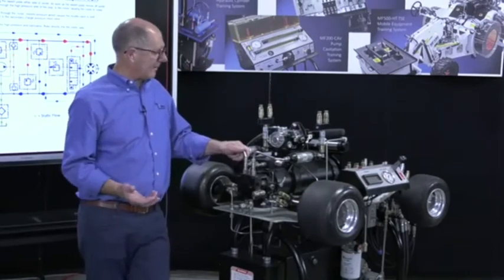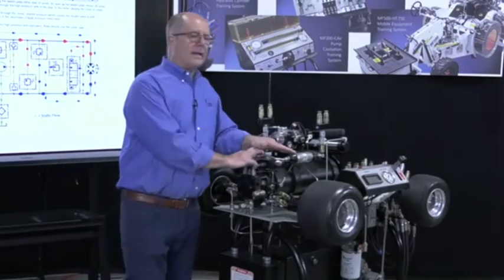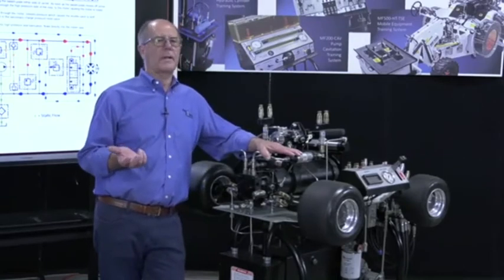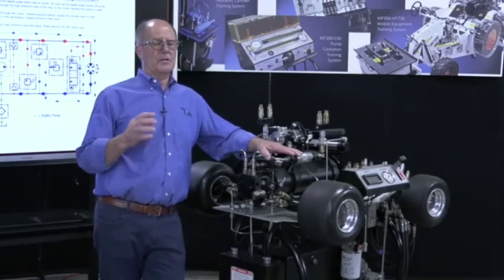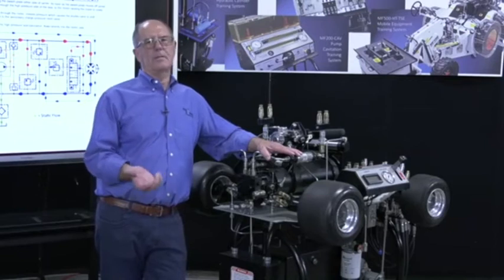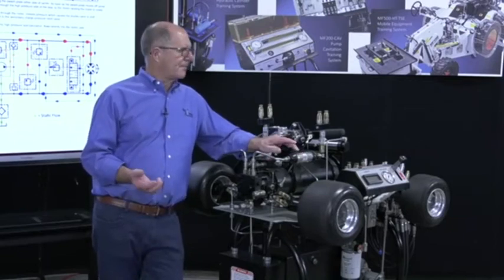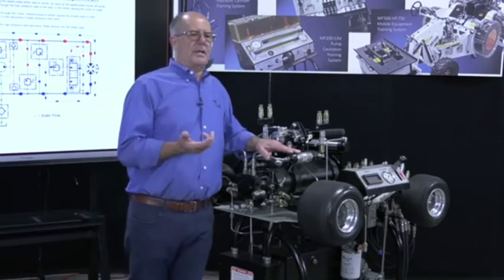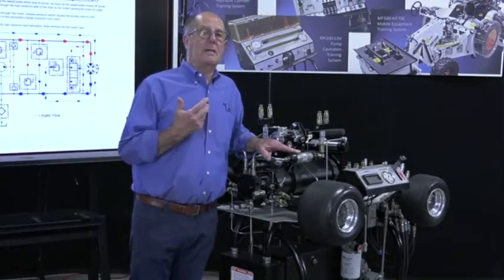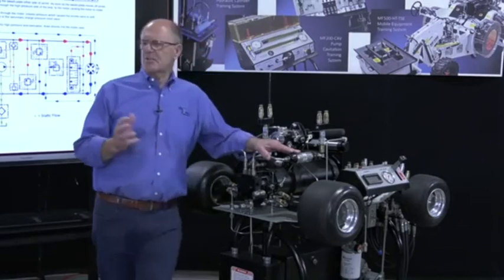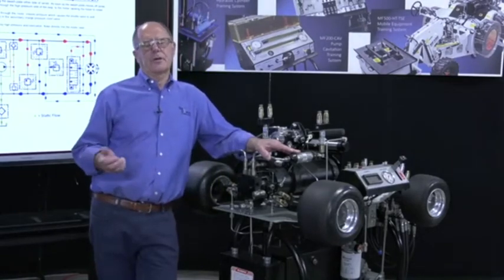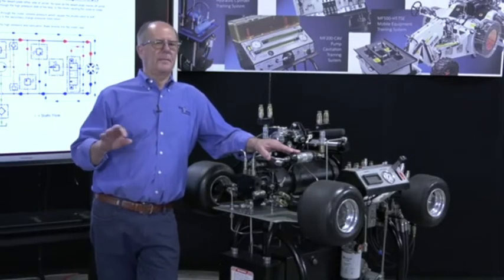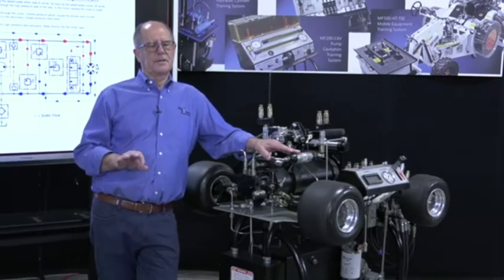The other thing that's unique is that when you're testing a hydrostatic drive, testing is a whole different ball game, especially when you're looking for wear in pumps and motors. One of the important things is to always test in the direction it spends most of its time in. And that applies to so many components, like cylinders, for example. You see so much stuff on the internet about testing hydraulic cylinders.